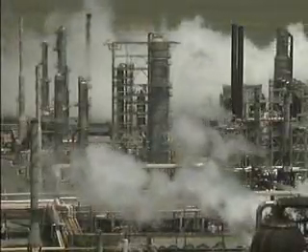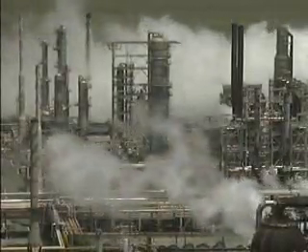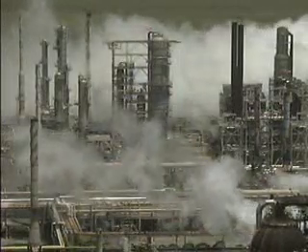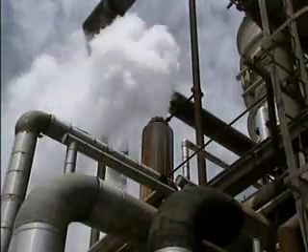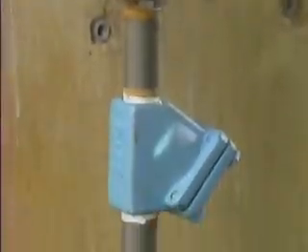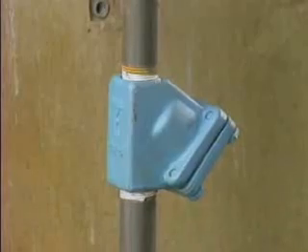Industrial facilities use steam both for heating and for performing various process operations. As the steam gives up heat, it cools and forms droplets of water called condensate. Accumulated condensate in a steam system's piping can cause a number of costly problems. So to maintain efficient, reliable operation of a steam system, condensate must be removed without allowing valuable steam to escape. A device that's commonly used for this purpose is a steam trap.